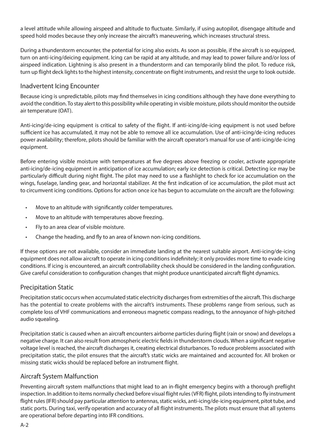Inadvertent icing encounter. Because icing is unpredictable, pilots may find themselves in icing conditions although they have done everything to avoid the condition. To stay alert to this possibility while operating in visible moisture, pilots should monitor the outside air temperature, OAT.